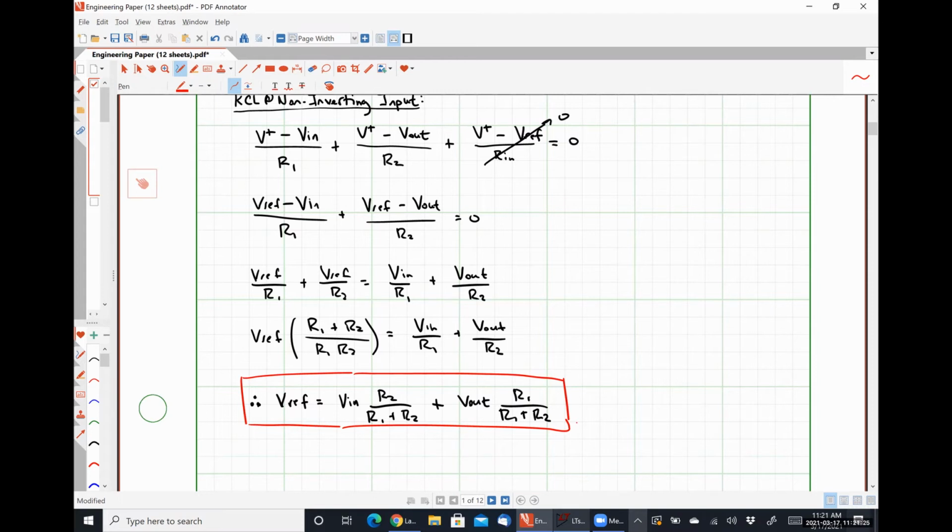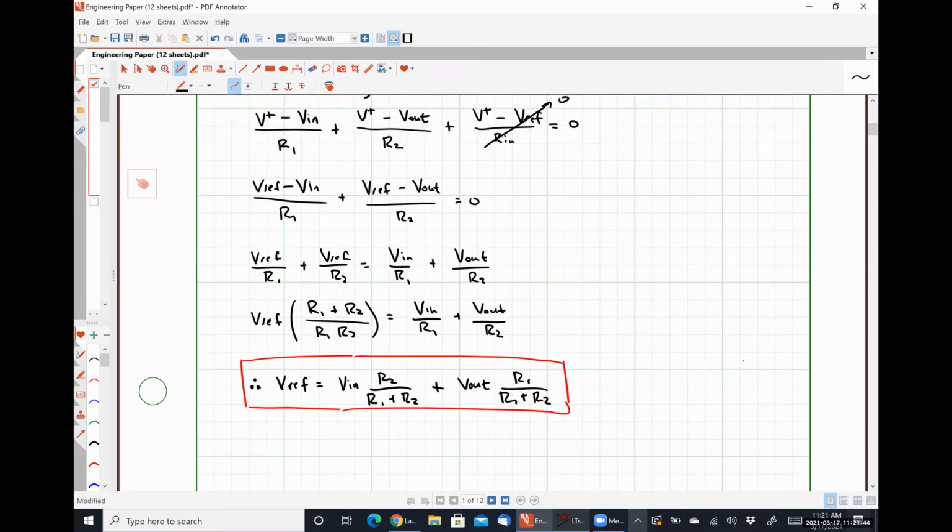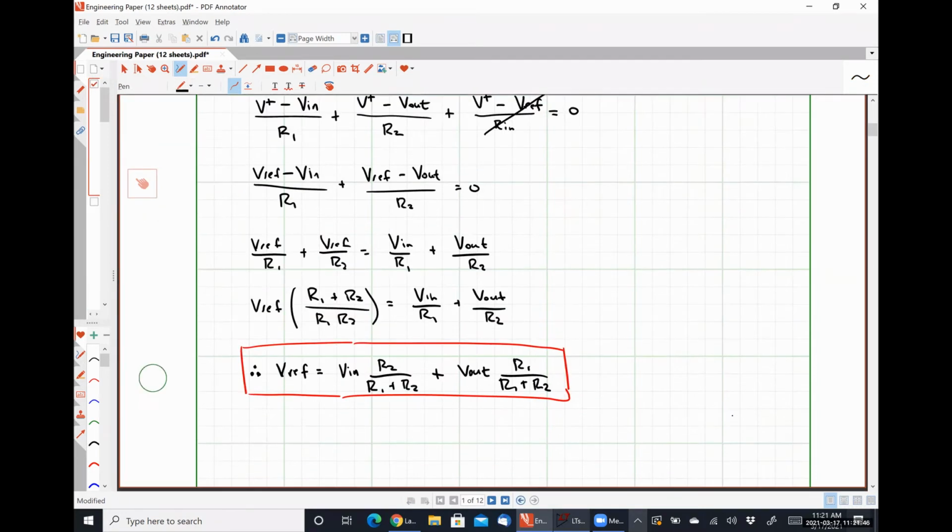It can't be any value in between for more than a fraction of a second. It's always going to settle to VCC plus or settle to VCC minus. So from this, we can determine our trigger levels.